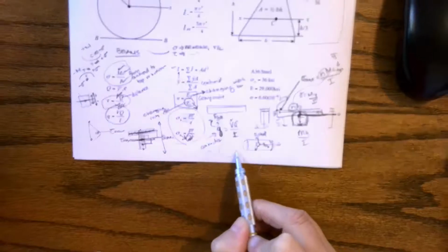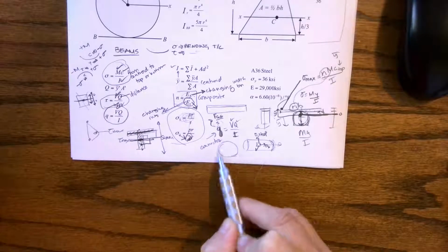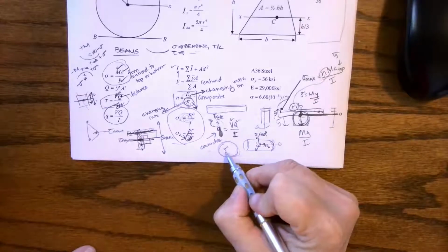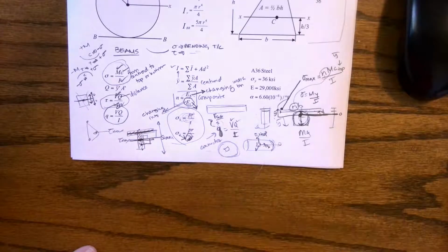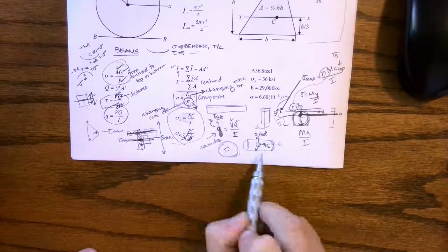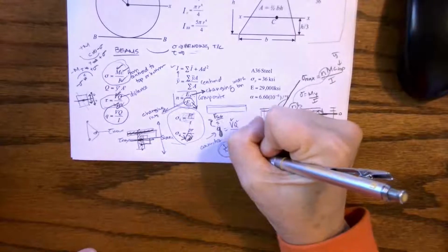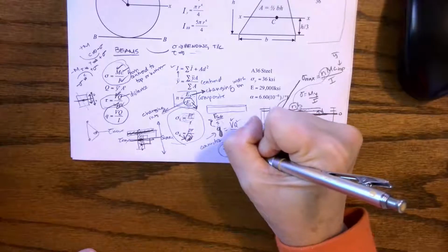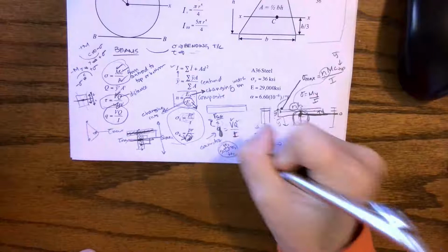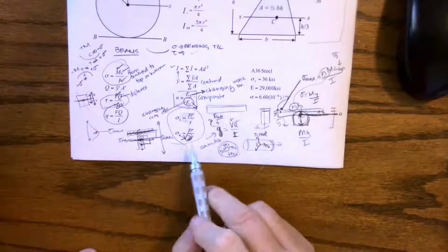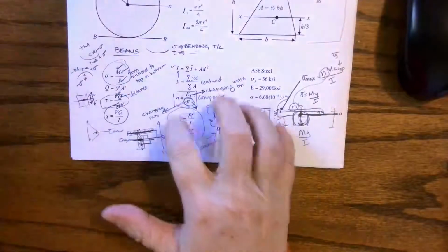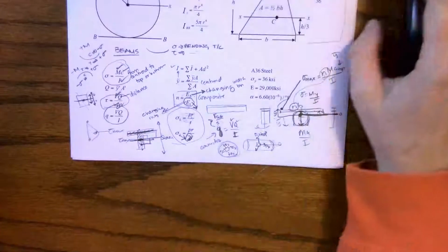If we have a perfectly circular container, spherical, it is the most, think of it, it's the most efficient shape. You don't see them very often because they're much harder to make than a tube. So this is all going to be stress 2, stress 2, stress 2, stress 2. It is all the longitudinal. It's super efficient. It's the smaller stress. So make sure you understand what goes on in each of these equations.